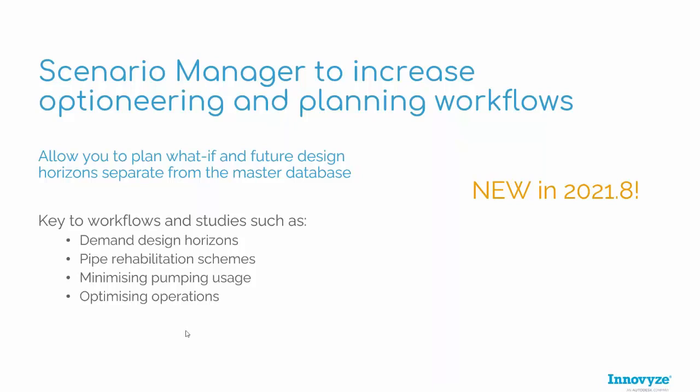So what this allows you to do is plan and have lots of different scenarios, for future scenarios, for what-if scenarios, for design scenarios, and to keep those separate from your base model. So instead of having to try your scenarios for pump sizing or pipe sizing or PRV set points by creating multiple base models, you create multiple scenarios which are associated with that base model.